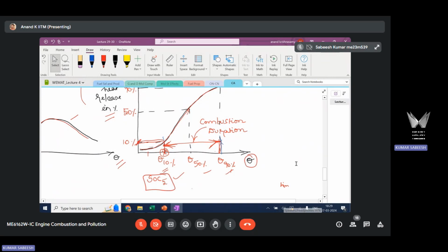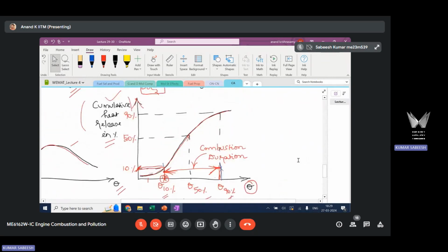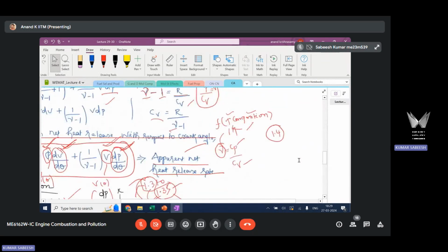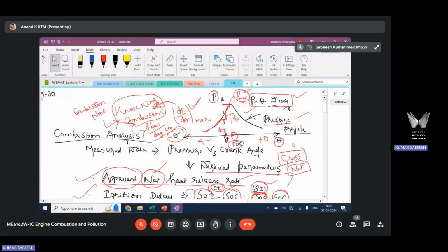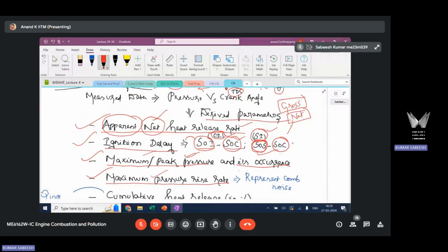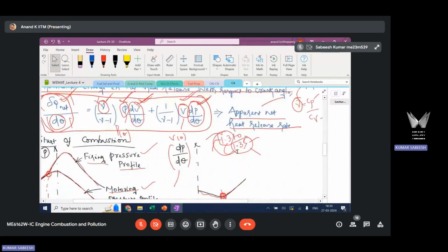I have a follow-up question here. Among these different criteria that we use to get the start of combustion, you need to know start of combustion to get the ignition delay. Without start of combustion, you cannot find this parameter. This is an important combustion parameter, ignition delay time. For that, you need this information, start of combustion. So my question to you, based on the discussion just now concluded: among the 5 criteria we discussed, which one do you think is more accurate to determine start of combustion?